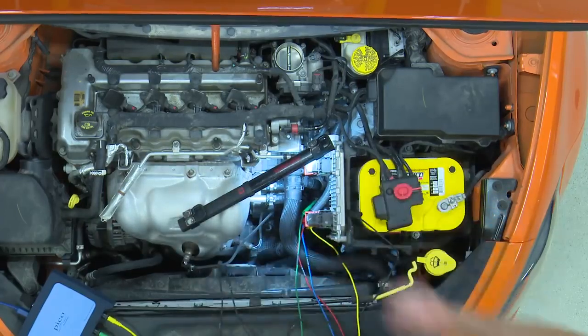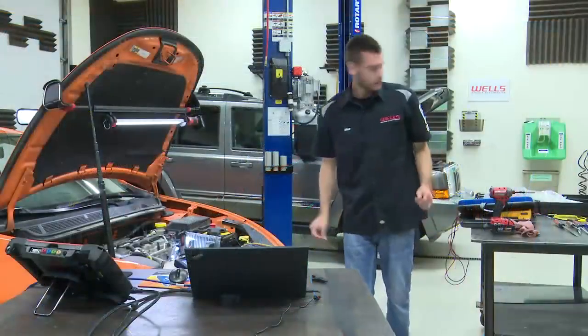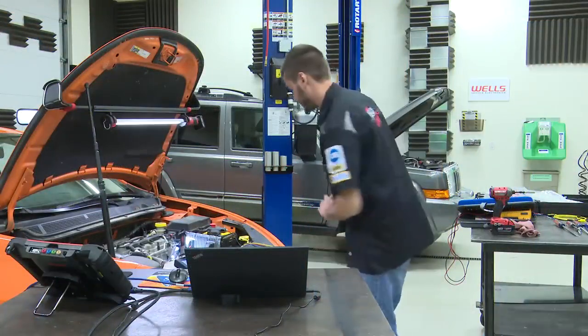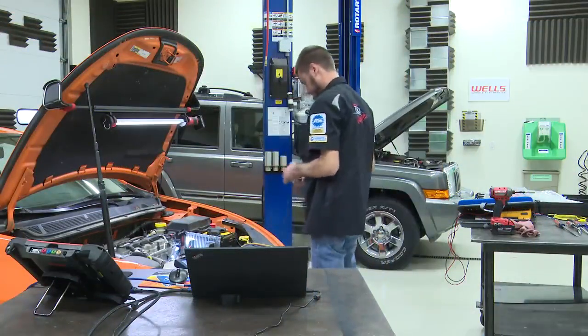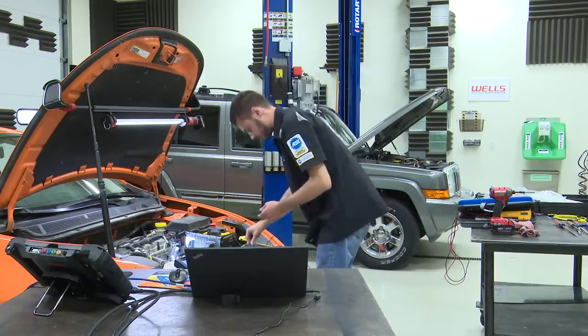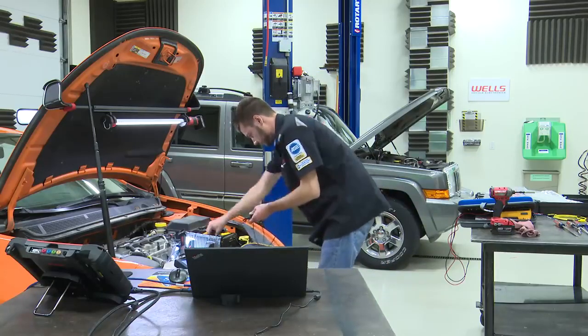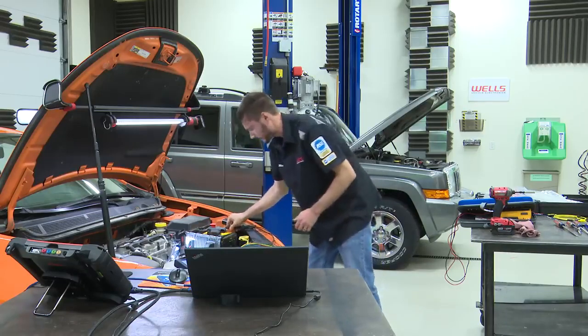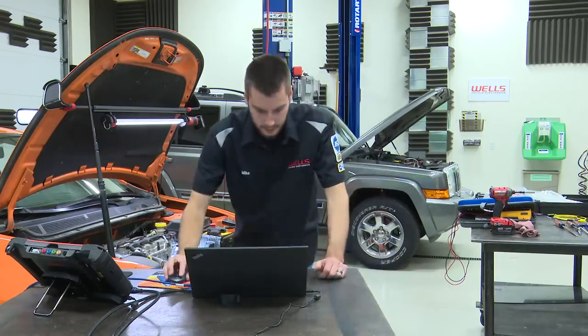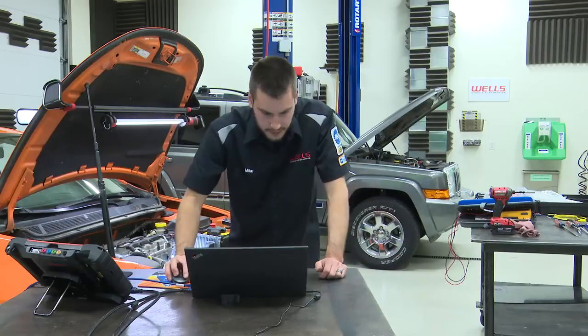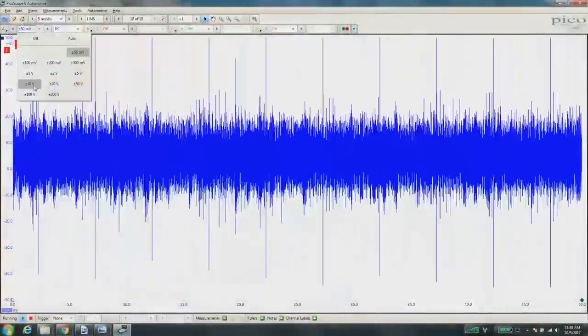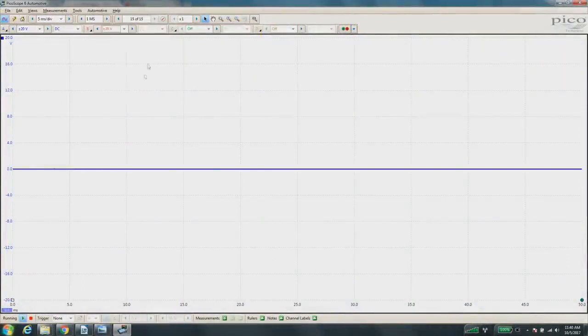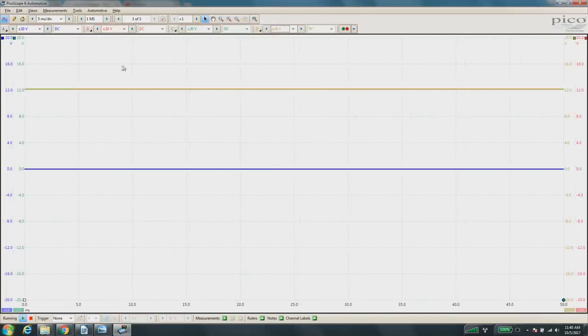All right, I think all of our signals are now back probed. Let's throw a ground lead on this and let's see what it looks like on the scope. Okay, that looks good. Let's see what we got here. Let's turn our scope on. Let's start everything at 20. I'm thinking this is probably a 12 volt. Could be something different.